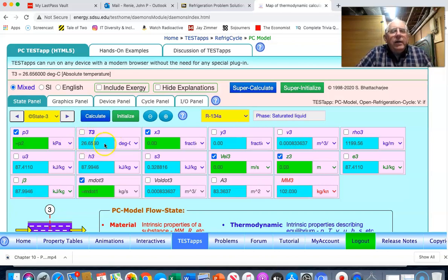So we're going to say that our cooling water comes in, let's say, at 15 degrees Celsius. Now we could actually come in a little bit higher. If we are using a counterflow heat exchanger, we can have a portion of the heat exchanger wherein the highest water temperature, after it absorbs heat and rises at least 8 degrees, is at the portion associated with the incoming refrigerant where it is the highest. But we'll go ahead with 15 and make sure that it doesn't get any higher than 23.